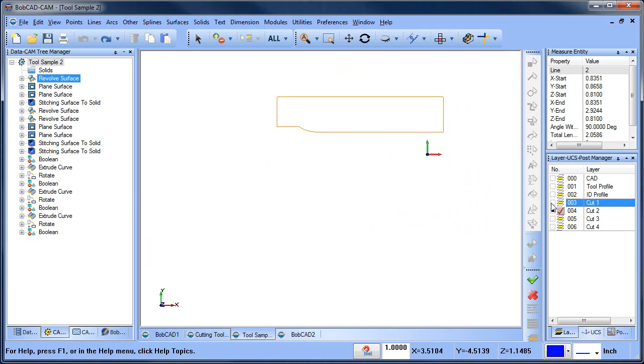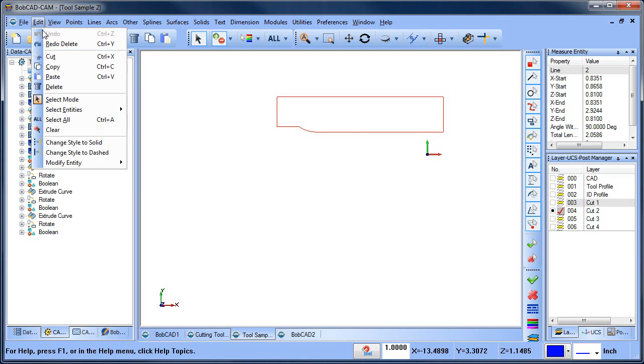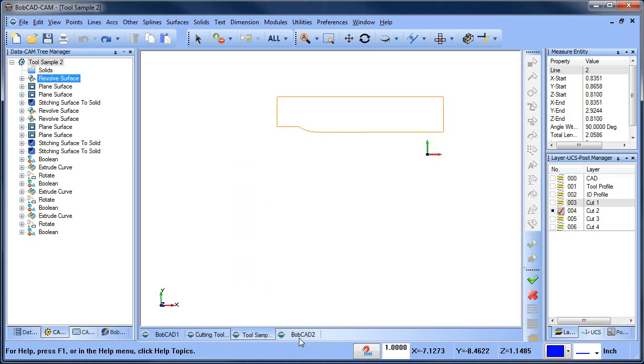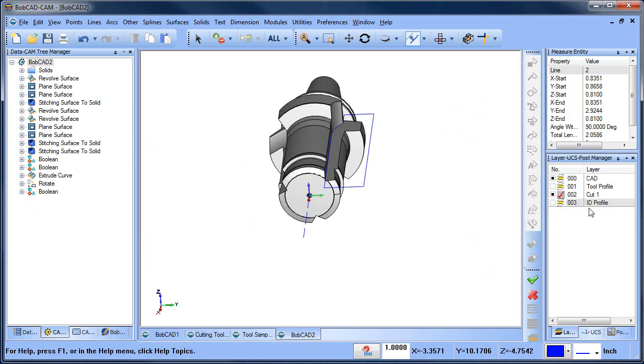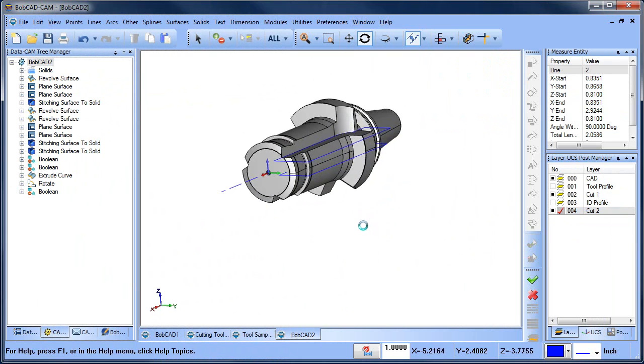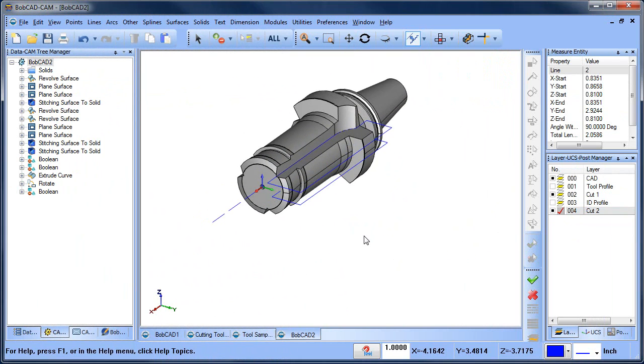All right, so moving forward, the next one that we have here, we'll just do cut 2. Again, cut 2, this has come off the drawing, and then we measured the depth from the end view. So I'll just copy this geometry here and come over to here, and then we'll add another layer, cut 2. When you copy and paste, if you make the layer active, that's the layer that it will be created on. And you can use Control-C and Control-V as well for copy and paste.